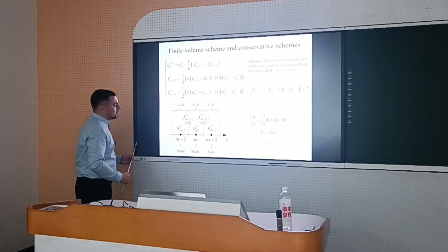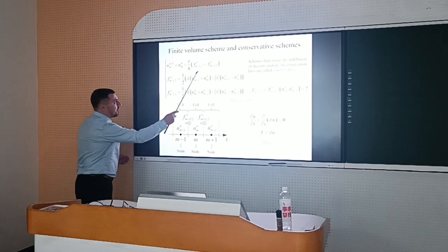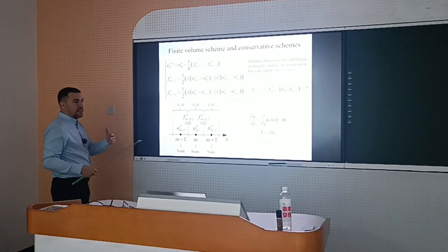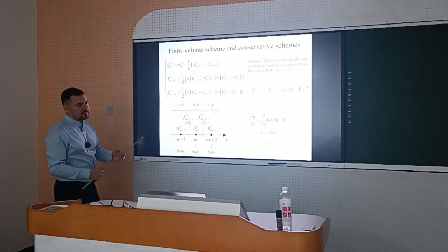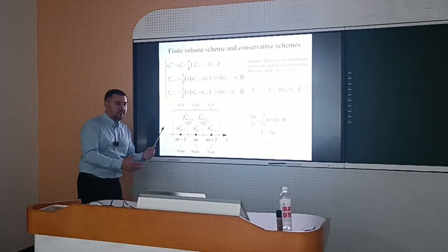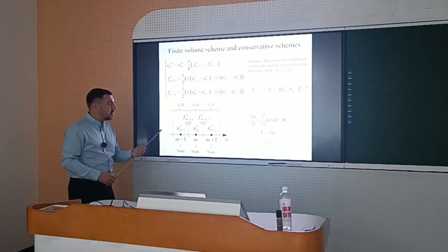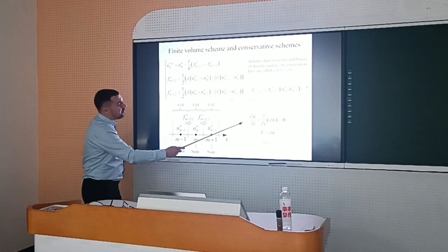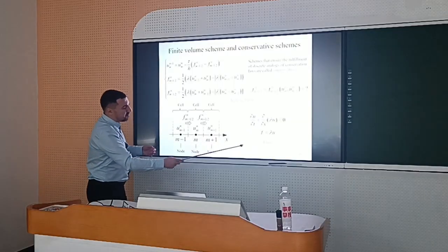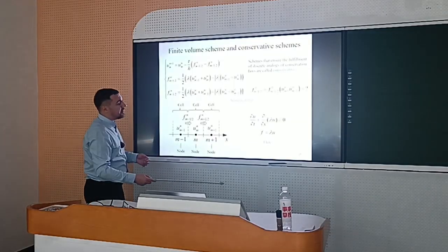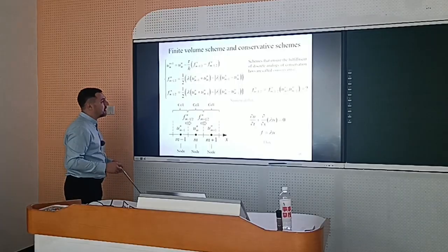And this finite volume formulation differs from finite differences, because in finite differences we just approximated our derivatives, in time and in space, and that's it. But here we do not approximate the derivative of our function. Instead, we work with flux to get the numerical flux.